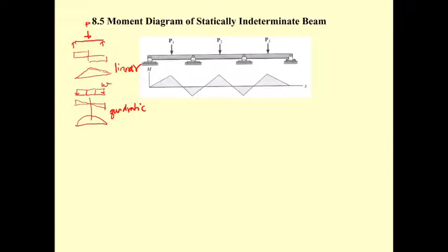That is a good thing that you are supposed to observe on this. Now, if the beam is statically indeterminate, you may have the moment here of 0 because there is no external moment, but the moment at the internal support is going to be a negative moment, and the moment near the middle of the beam is going to be a positive moment.